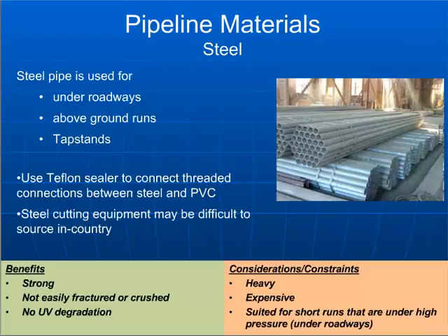The challenge with steel is that making the connections is not always easy. You've got to actually cut the threads, or if you cut the pipe, then you've also got to cut your own threads, and that tends to require some relatively specialized equipment. Now, people have been using steel pipe around the world for a long time, so you're always going to be able to find somebody that can thread pipe for you, but it may not be out in the village. It may be in the regional city or provincial city where you actually bought the steel pipe.